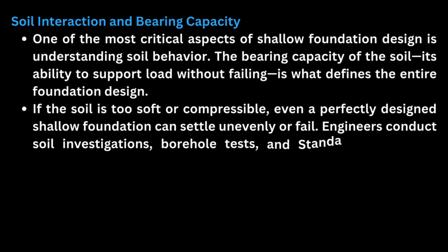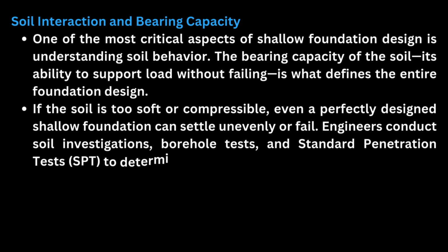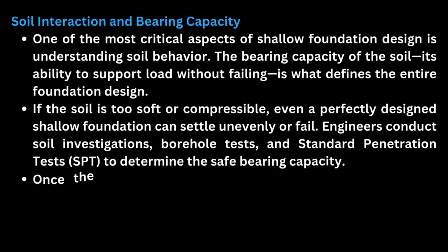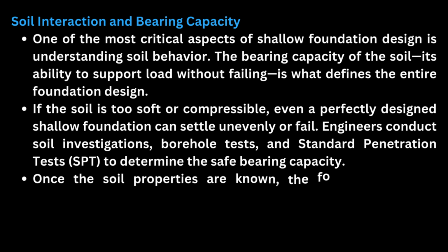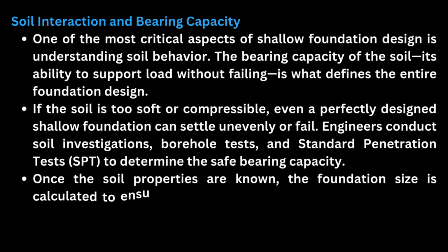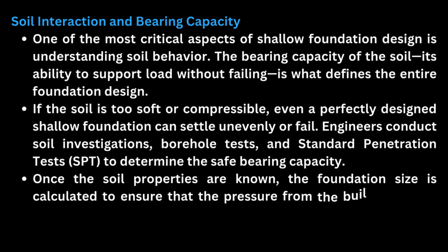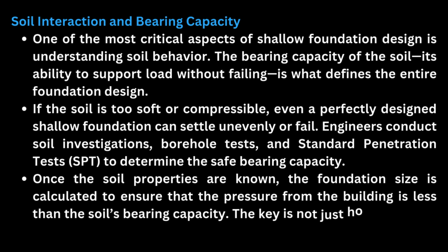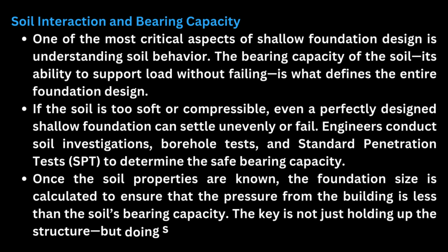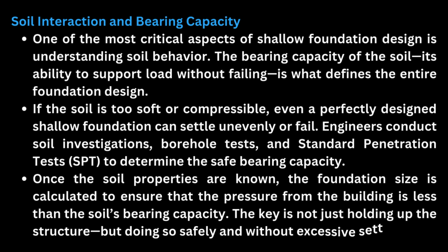Engineers conduct soil investigations, borehole tests, and standard penetration tests, SPT, to determine the safe bearing capacity. Once the soil properties are known, the foundation size is calculated to ensure that the pressure from the building is less than the soil's bearing capacity. The key is not just holding up the structure, but doing so safely and without excessive settlement.